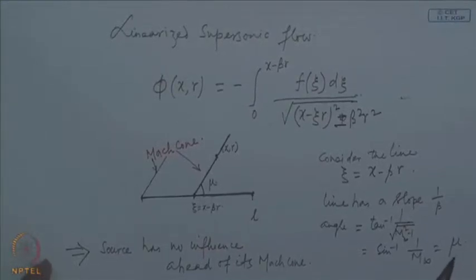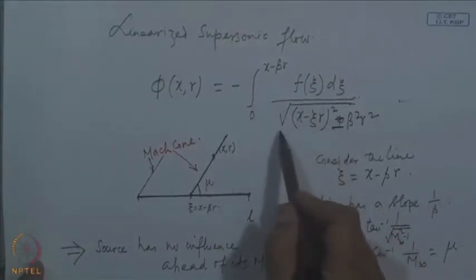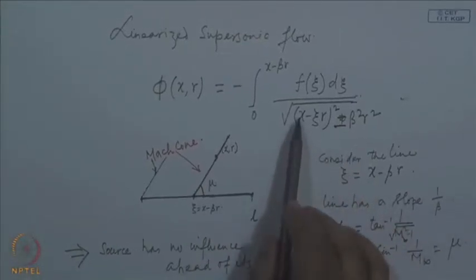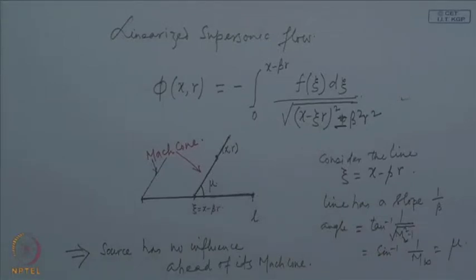Now, this part of the solution we obtain mathematically, and this is the physical interpretation of this mathematical solution, and we clearly see that this is what is required in case of a supersonic flow. As we have discussed earlier, the supersonic governing equation, even for the linearized perturbation problem, is hyperbolic, which has characteristic directions and represents a propagation problem, for which boundary condition at the infinity boundary is not required.